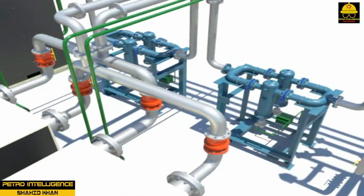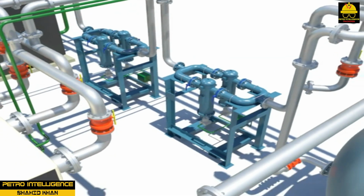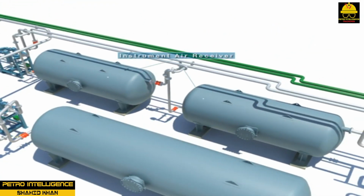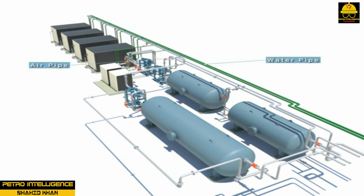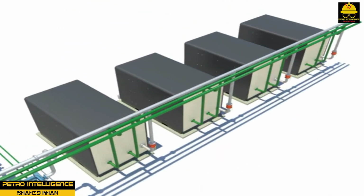It is important to maintain the instrument air system pressure at its normal controlled pressure of 105 psi because some control valve actuators begin to malfunction when the pressure drops below 60 psi. At some locations, the plant instrument air system is protected against pressure failure by a tie-in to the nitrogen N2 system. Because of safety concerns, nitrogen is admitted into the instrument air system only during an emergency. An alarm or alert system is in place to warn all unit personnel whenever nitrogen is added to the instrument air header.